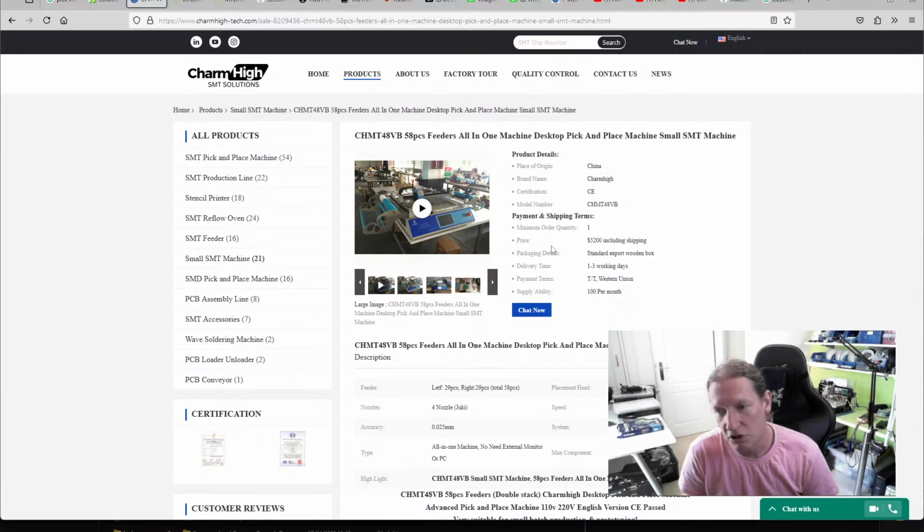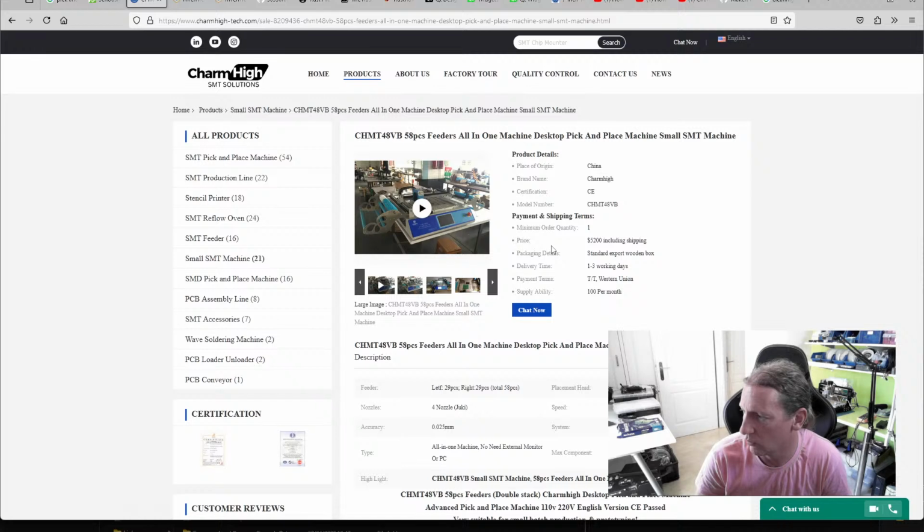It also allows you to do just-in-time manufacturing. So instead of having to make all of your products up front and just have them ready to ship, you just make like 30 at a time, which is fine. You can get that done in a day with a pick and place machine, even on a 2-sided board. And then you've got stock there waiting to sell, and you've not used up your components. And if you need to make changes to the design, you can do that. So it's essentially a quick way of going from prototyping a product into actually having the final product out there. And the prototypes end up being exactly the same as the final designs.